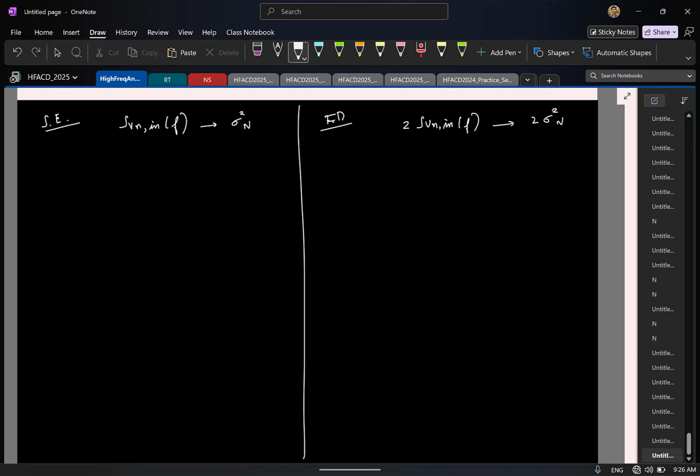the absolute noise power. What actually matters is signal to noise ratio. Simply because let us say you can have one system where the noise is some 10 microvolt square noise power. Another system can have noise power of 100 microvolt square. But this doesn't matter because let us say the maximum signal power the first system can handle is only say some 50 microvolt square. Then you see that my signal power and noise power are very close. I will not be able to differentiate what is signal and what is noise. Whereas in the second system, if this can take signal power of 1 millivolt square, this is significantly better. So that's why absolute noise power makes no sense. You look at how much noise is added with respect to my signal.